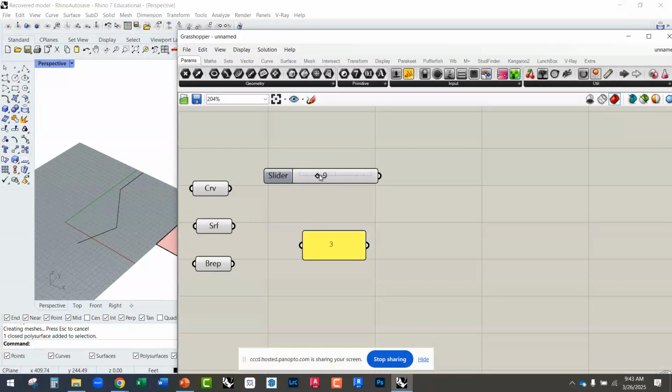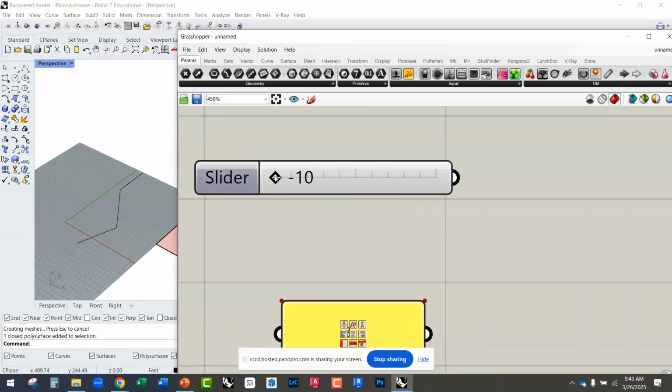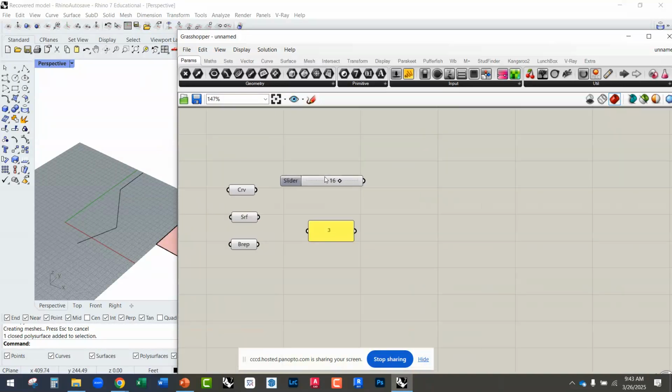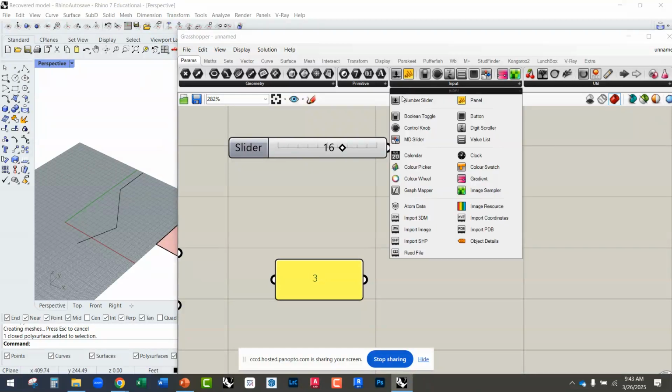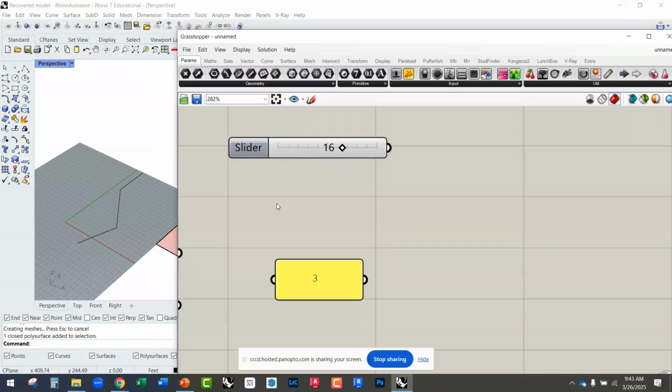All right, so now notice this number slider goes from -10 all the way up to 30. So you can control the slider that way. And again, I went to Input, grab Number Slider. You can also double click on the canvas and just start typing a number. So let's say I want that similar range. If I just type 25, then click, it'll give me a value from 0 to 100, and it'll include that number of 25 that I included.